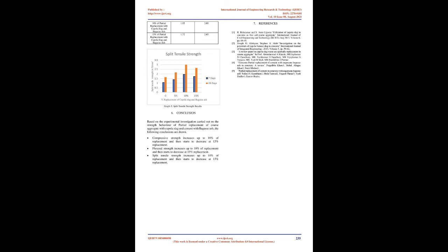Flexural strength. Flexural testing is used to determine the flex or bending properties of a material. Sometimes referred to as a transverse beam test, it involves placing a sample between 2 points or supports and initiating a load using a third point or with 2 points, which are respectively called 3-point bend and 4-point bend test. Maximum stress and strain are calculated on the incremental load applied. Results are shown in a graphical format with tabular results including the flexural strength, for fractured samples, and the yield strength, for samples that did not.